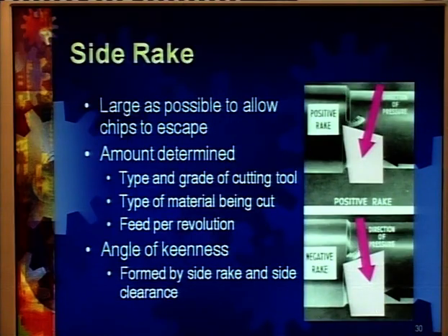Suppose we are to machine a gear flank, whereby the load coming onto the workpiece will not be continuous but intermittent. It will then have an effect just like the striking of a hammer, and if the side rake angle in this case is much more, it will result in the immediate breaking out of this particular tip. So, depending upon the geometry of the cutting of the workpiece, we will decide whether the side rake angle should be greater, positive, negative, or flat.